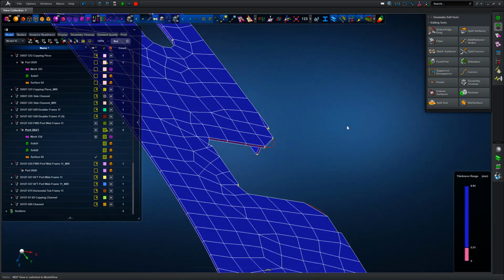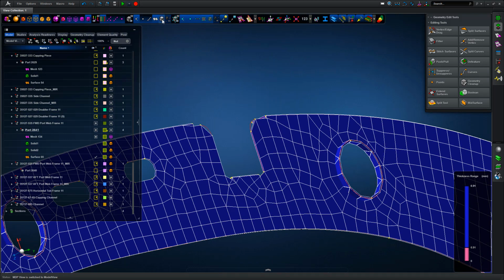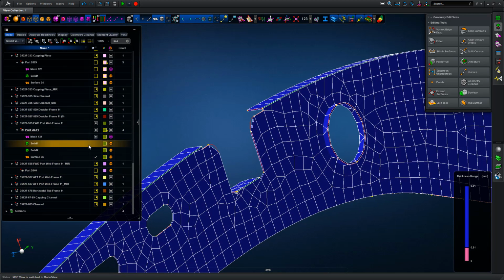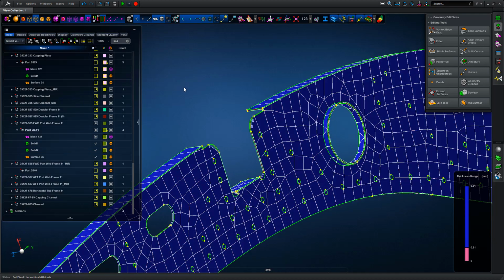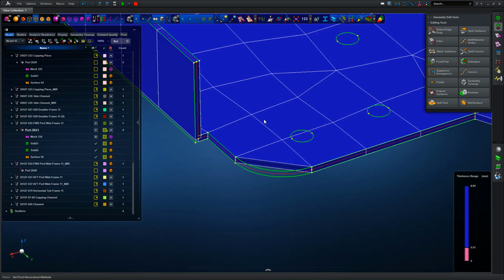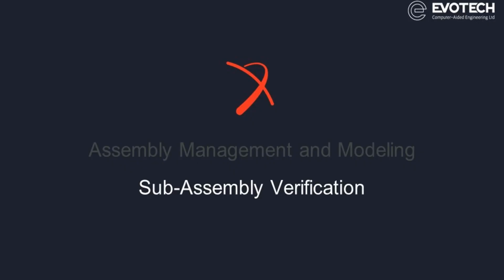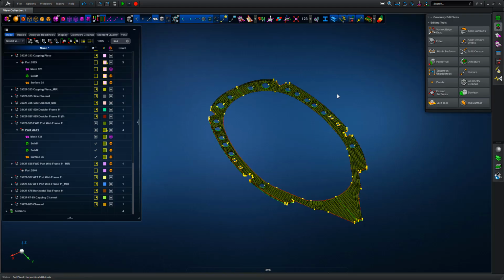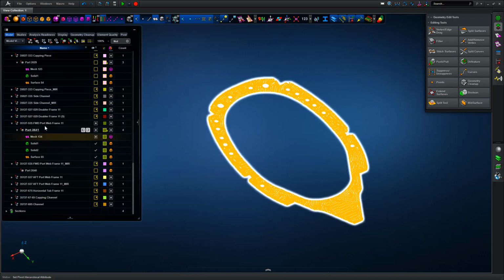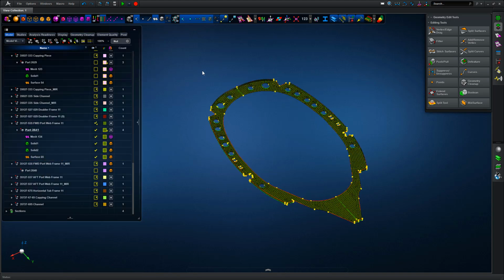If you remember from the mid-surfacing operation, we had auto thickness turned on, so the shell properties have been populated by that auto thickness parameter, and we can look at the solids overlaid over the resultant shell mesh definition. We see we've got a perfect definition in terms of the shell property to 3D CAD thickness. So very straightforward. Once we have that single part or single subassembly defined, we can verify the model response at this level before we start to look at the overall assembly definition.